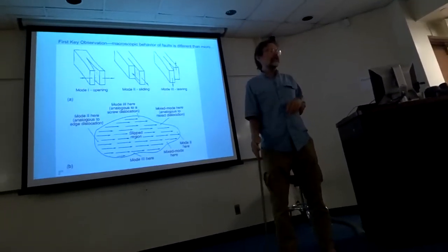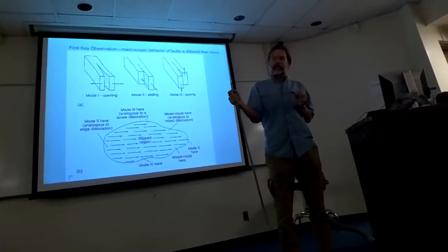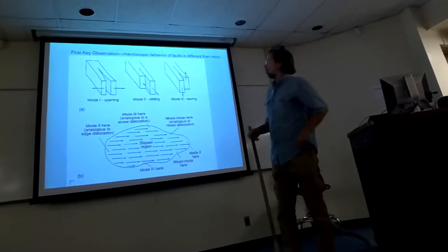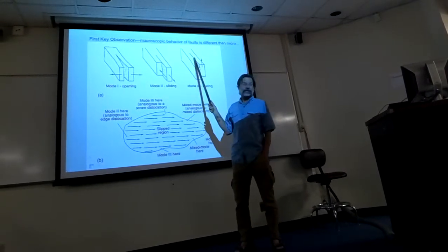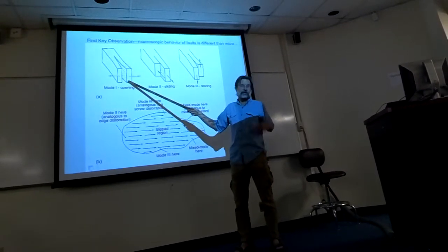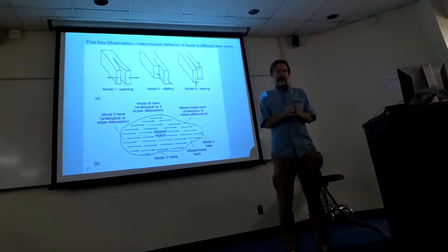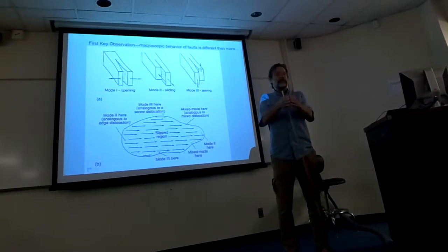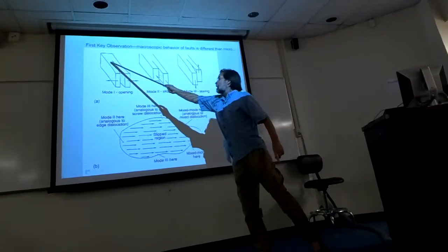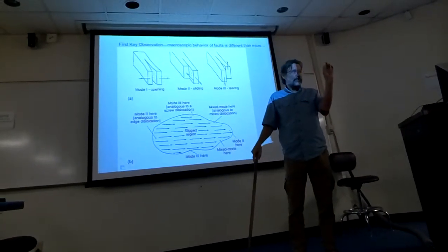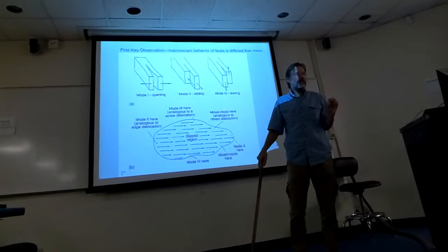And you can show that theoretically. But the important point is that there's a magnification of stress effect at the tip of the fracture. In fracture mechanics, that type of fracture, the windshield type fracture, is what's called a mode 1 fracture, which means that kinematically the fracture forms by an opening in the fracture. And so it propagates by the concentration of stresses at the tip, which make the stresses go tensile. And so the fracture propagates at that fracture tip, even under very low stresses.